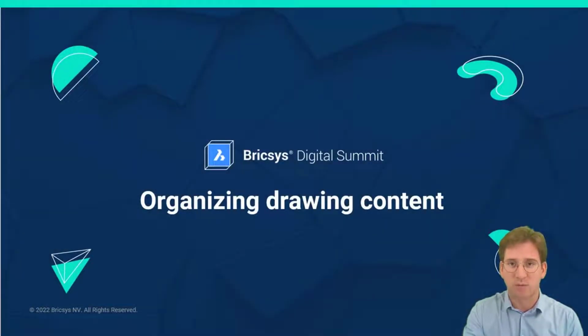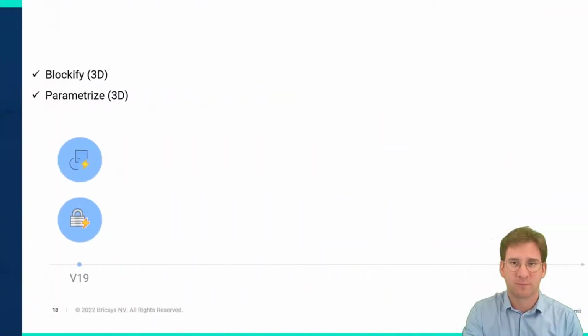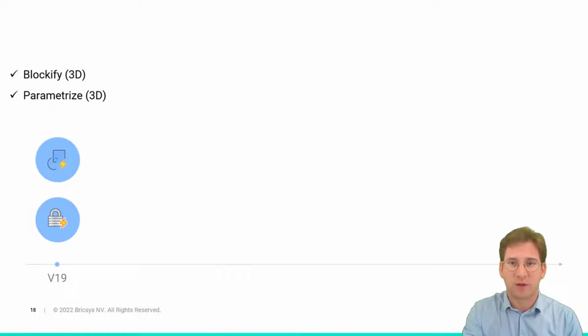As a final design workflow, we at BricsCAD are eager to deliver features and functions that bring order to the chaos. We help our users to organize drawing content in a more structured, logical, and compact way than any other CAD system. We started this journey back in 2018 with the release of BricsCAD V18. There, the first Blockify tool was released, at that point only supporting 3D solids, to automatically and quickly find equal solids in model space, and to replace them with block refs.